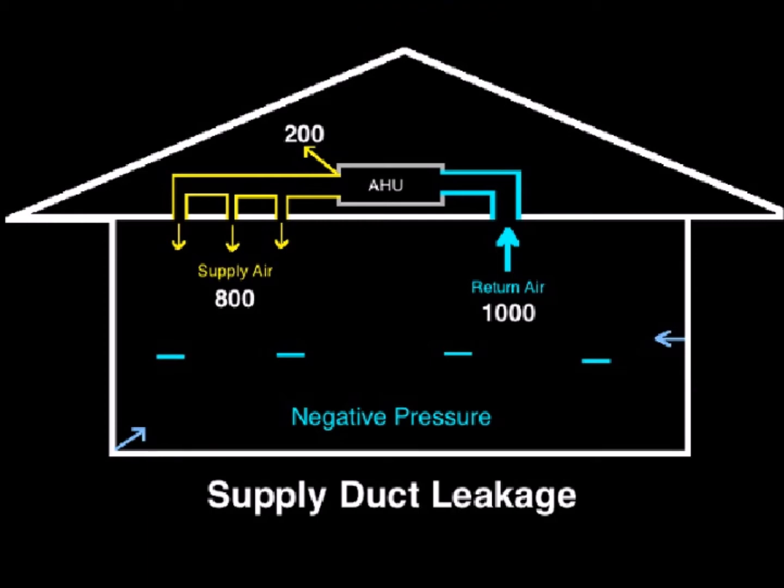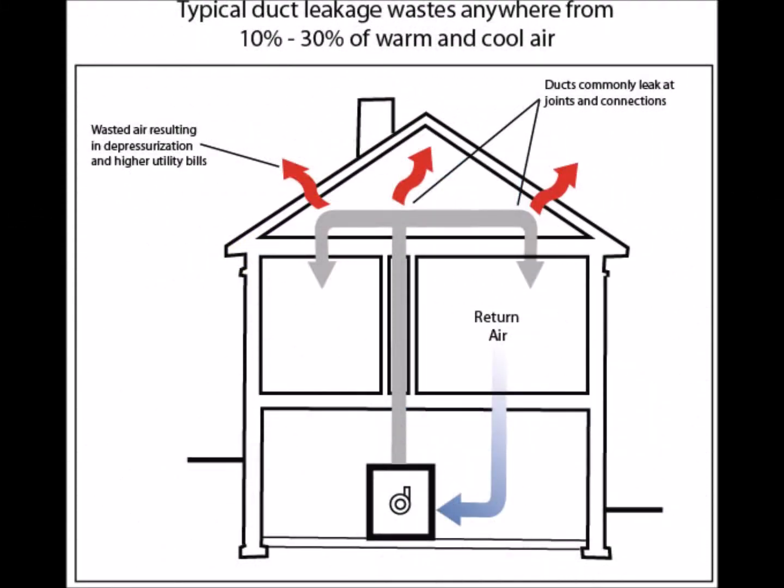You may see foil-faced batt insulation used in a cathedral ceiling because it has a 0.5 perm rating and provides the permeability often required for use in ceilings without attic spaces. You should see vent baffle installed between the insulation and the roof decking to make sure that proper ventilation is maintained. If the roof framing at the cathedral ceiling cannot provide enough room for proper insulation and ventilation, then you